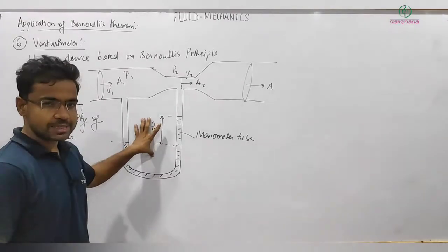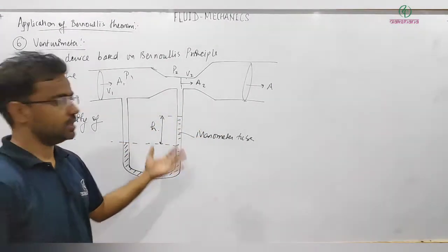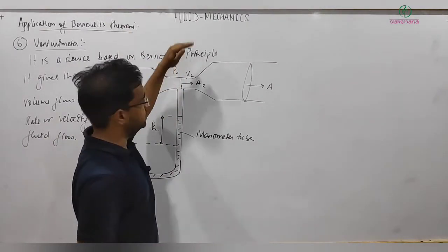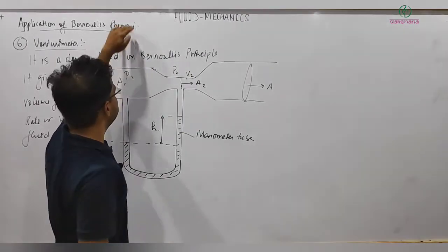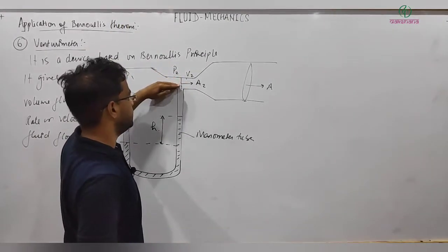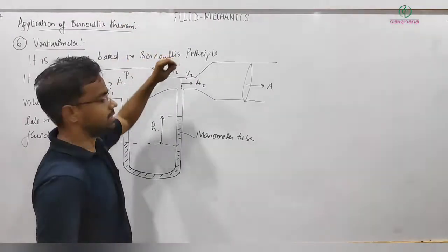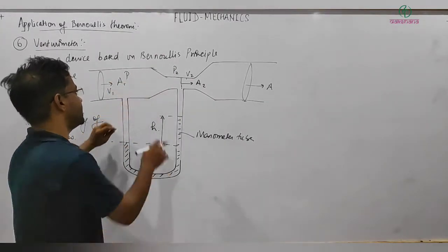One setup is this, another setup is also there. I will tell you how exactly. That is also simple, where one tube is connected here and another tube is connected here. So the same liquid basically rises. Here pressure is high, so the liquid will rise up to more height compared to here where pressure is low and the liquid will rise up to less height. So again the difference in height is measured, and that gives you the difference in pressure.